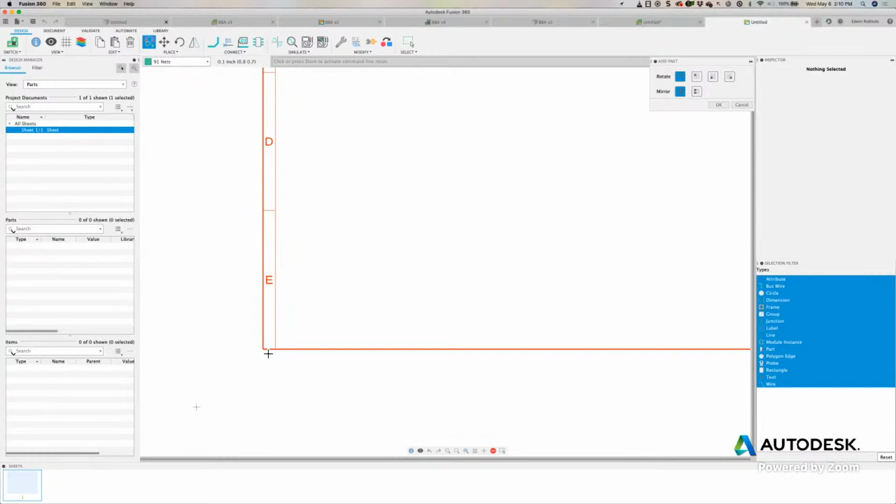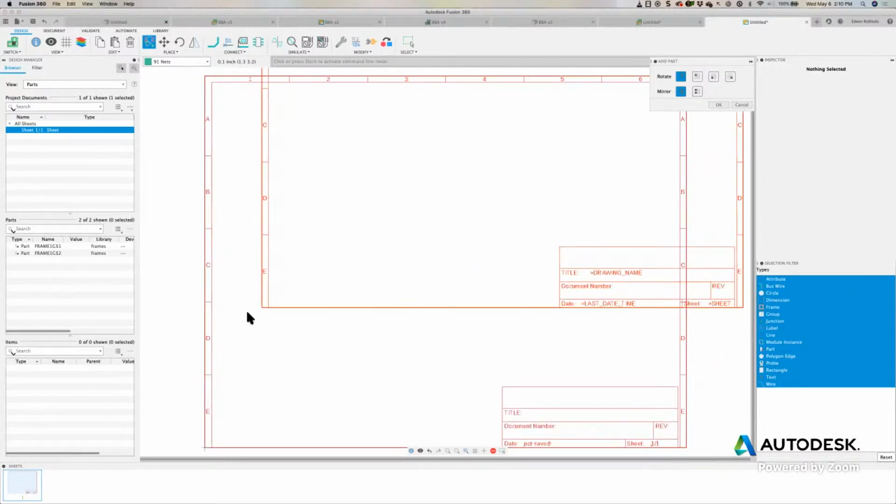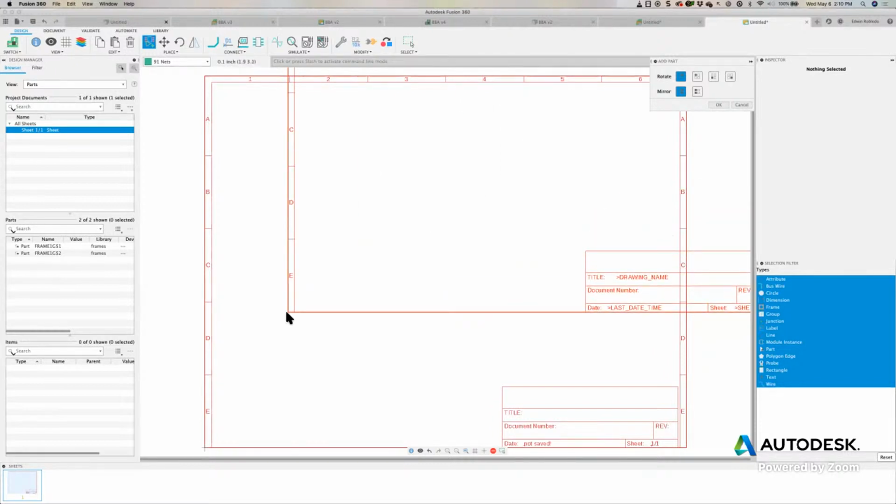And we always work on the positive side of the coordinate system. So I'll place my frame right there, okay, and I'll go ahead and do a zoom to fit, as we do here. And you'll notice that I have another frame on my mouse cursor, which is kind of neat. I don't need it right now, but the idea is that if you were still using components, you want another. It's quite common with passive parts like resistors that you're going to be using multiple resistors. So you click on one, you automatically get one on your mouse cursor. You click on the next one, you get another.